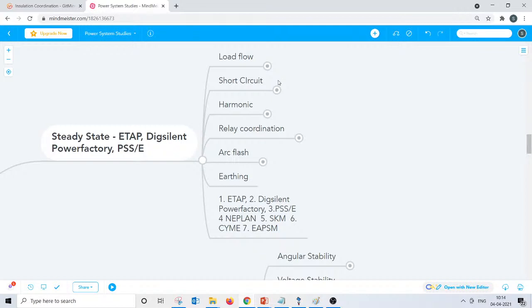At the same time, this should ensure that the short circuit current is well within the limit for the LV side of the switch gear of the transformer. So why are we doing power system studies? To optimize the parameters rather than justify the parameters. Most of the time we are doing it to justify whether the parameters that have been selected are